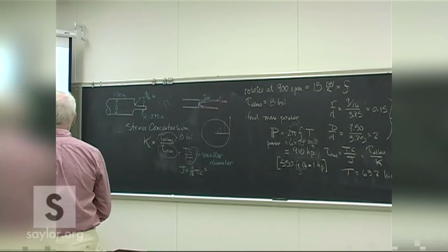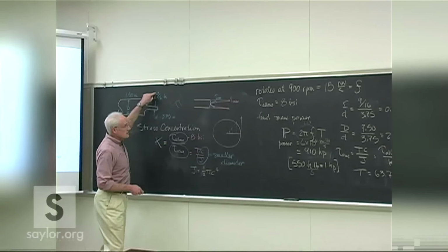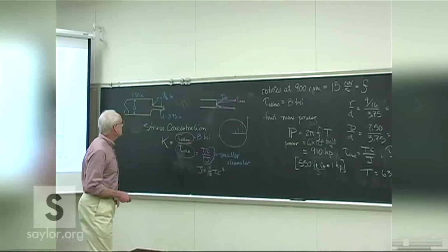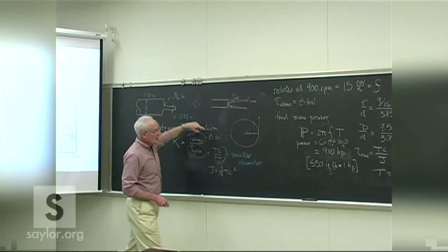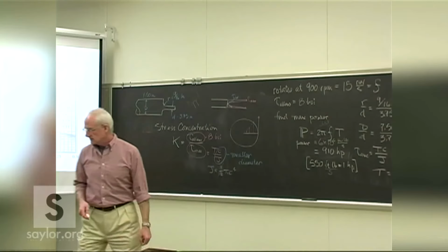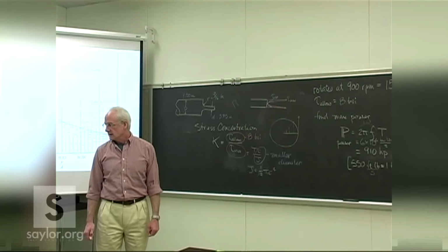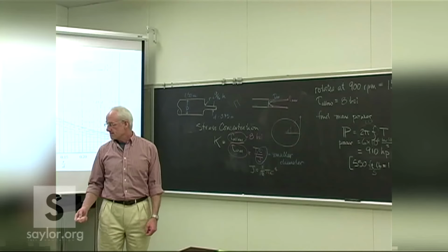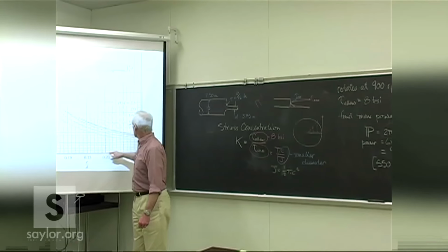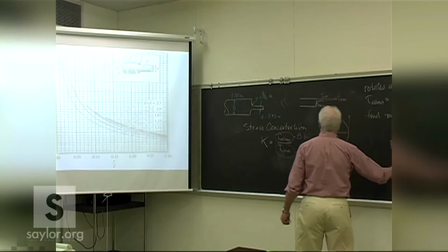Okay, fine. All right, increasing the fillet radius to just a little bit more, to 15/16, raises the power by about 11%. So then it's an engineering design decision if that's worth it. Yeah, it drops your K value. If you increase the radius, you go up here, the K value drops, and you get more power out of it because you can put in more torsion.